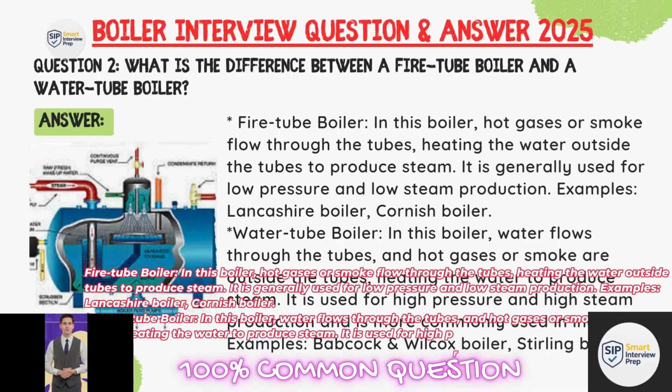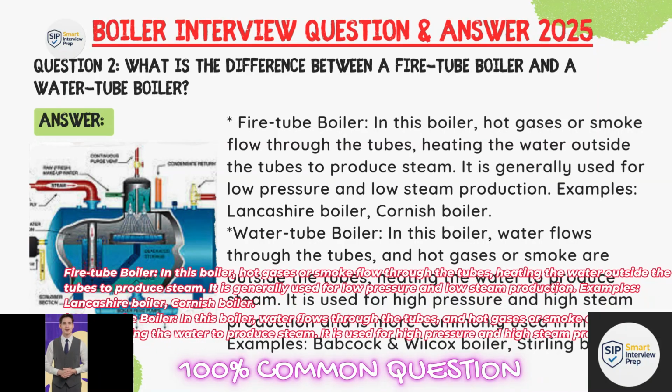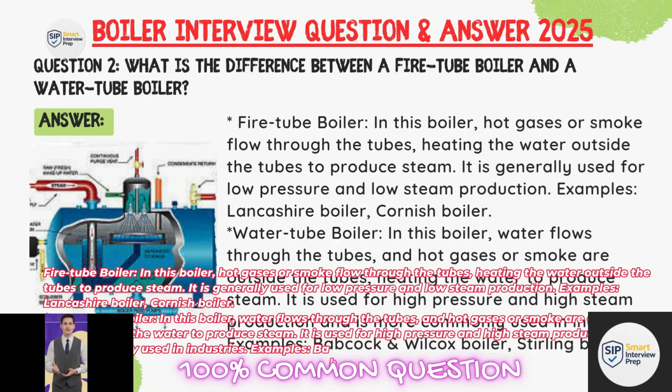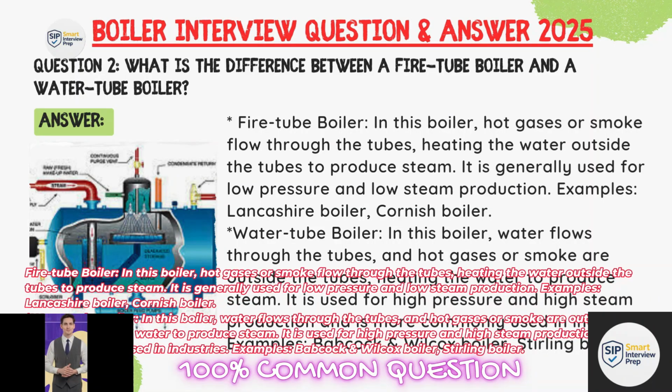On the other hand, in a water tube boiler, water flows through the tube and hot gases or smoke are outside the tube, heating the water to produce steam. It is used for high pressure and high steam production and is more commonly used in industry. Example: Babcock and Wilcox boiler.